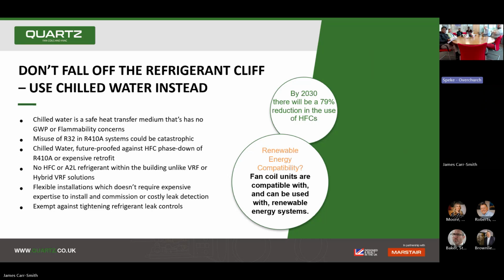One of which, when we talk about VRF, as we mentioned here, is flammability. So flammability is a concern. Some of the legislation at the minute will stop you putting some of the mildly flammable refrigerants into a system in volume. A typical VRF system might have hundreds of kilograms. You will not be allowed to do that as part of the legislation, using something that's mildly flammable, for reasons of obviously creating explosions. So there is the flammability concern of it.